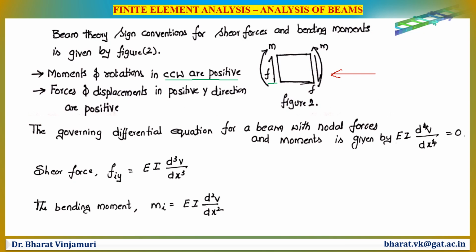So if there is any moment in clockwise direction, as you see here, this is considered as a negative moment, and the moment or the slope in counterclockwise direction is considered as positive. Similarly, the shear force, if it is directed in positive y direction, is considered as a positive shear force, and if it is coming down in negative y direction, it is considered as a negative shear force.